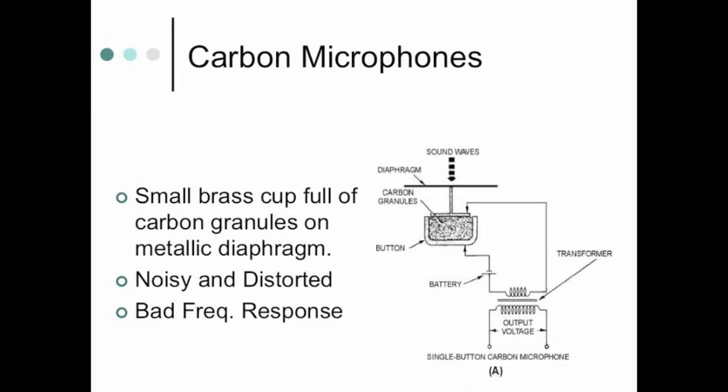Let's talk about the less quality types of microphones. These are the microphones that are mostly used in industrial uses. For example, in the 40s and 50s, those old-fashioned telephones with hard plastic receivers that would hang on the wall, they would use carbon microphones because they were extremely durable. Not very sensitive, but to pick up voice when you're trying to communicate over a telephone line, that's why you get this kind of a tunnel sound when you think of a telephone voice. Because the microphones weren't very sensitive and not very good quality, but they're extremely durable.